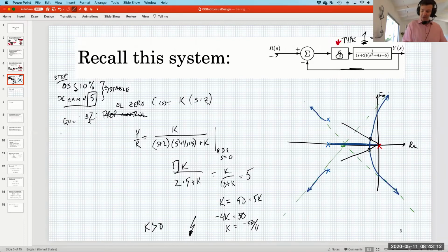And here we're running into about the bounds of our usefulness of root locus, because remember, root locus is really about how the closed loop poles move as one parameter changes. And right now, we have 2 parameters to change. But we can at least do our best. We can maybe set a couple values for z and draw several root locus diagrams, one for each of those values. So we'll start again with the plant poles.